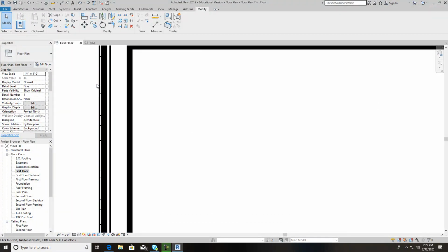However, this farthest point on this one is showing up as your exterior wallboard, or your exterior cover, which is either going to be like vinyl siding, wood shakes, or clapboard. Really, you need to be on the outside edge of your outside wallboard, like your plywood that's on your wall studs, and I'll show you that.